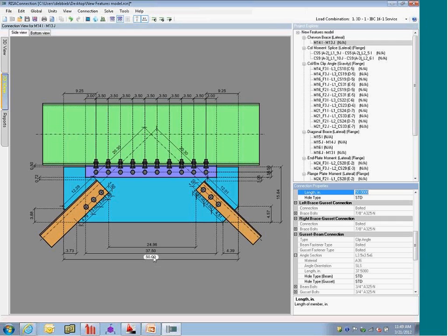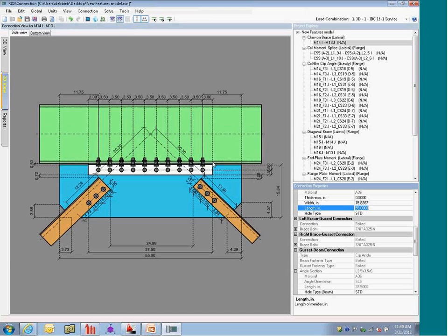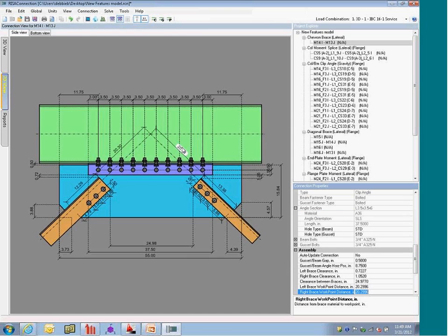For some reason, maybe the geometry is not working out for me, and I need to make this plate a little larger. I can increase that length of that connection to 55. Resize it, and maybe I can change this number here to 22, and it sort of bumps things down. So you can rework that direction. I'm going in to the central point, and you can see that lines up there. That center line is coming in right at the center point of the beam.